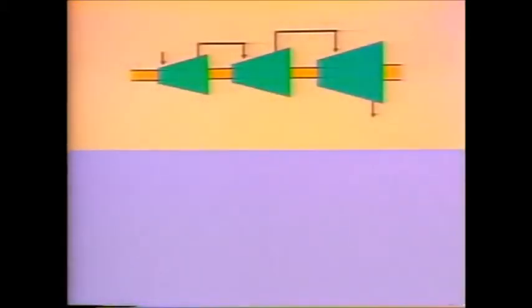So far, we've been talking about a simplified turbine. Most large turbines are divided into sections, and each section is connected to a common shaft. In this example, there are three separate turbine sections: a high-pressure section, which we abbreviated as HP, an intermediate pressure section, IP, and a low-pressure section, LP. At times, the different sections are referred to as separate turbines, HP turbine, IP turbine, and so forth. But operationally, they'll all make up one turbine.